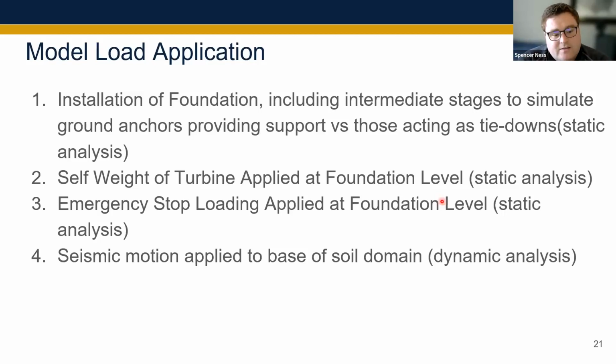We then applied the self weight of the turbine and the tower at the top of the foundation level. We didn't directly model the turbine itself, just given the computational effort that we were already going through, so we simulated the weight of the turbine just as a surface load. And then we moved into applying that emergency stop load, that overturning moment that gets applied as we apply the brake up at the turbine.